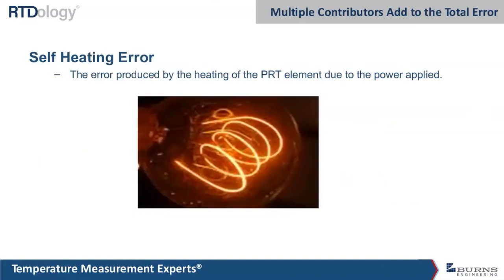Self-heating. RTDs are either just a coil of wire or just a little tracing of platinum on a ceramic substrate. So anytime you run electrical current through a wire, it's going to heat up. And it's no different for an RTD or PRT, which is platinum resistance thermometer. And that's going to give you a higher than actual temperature measurement.